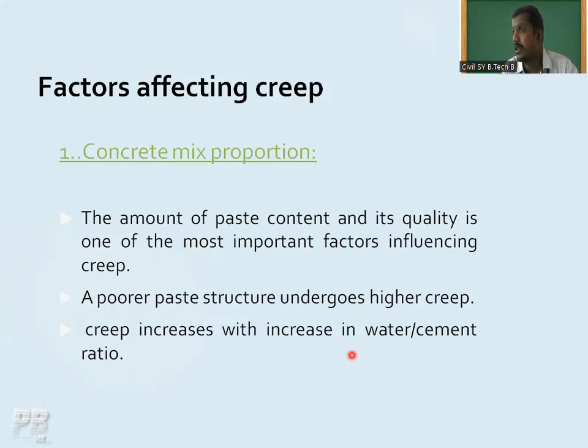As I told you in my previous session also, this water to cement ratio plays a vital role in chapter number 6 also, that is regarding durability. Then in chapter number 7, that is concrete mix design, it is not possible for you to prepare a concrete mix design without considering the water to cement ratio. So everywhere we require this concept. Keep the water to cement ratio as minimum as possible based on the design that you have prepared, or the minimum water to cement ratio given in your IS 456 2000 table number 5.